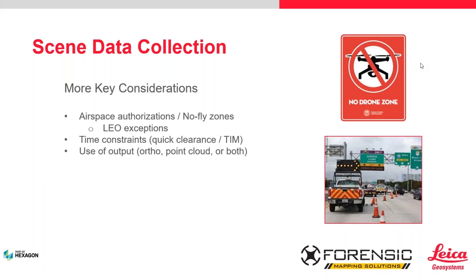Then we get into issues with airspace, what's called controlled airspace, areas where the FAA has determined that you're not going to be able to operate a drone, and that could be at certain altitudes only. It could also be because of what's called a TFR, or temporary flight restriction, which are used for dignitary movements, security for events like baseball and football, and other security issues for the country. However, as public safety, there is a way that you can get an emergency waiver, and it comes from a group of the FAA called the Special Operations Support Center. After the webinar, we are going to provide, in several methods, this information for anybody that wants it, with all the phone numbers and the procedure you need to follow.